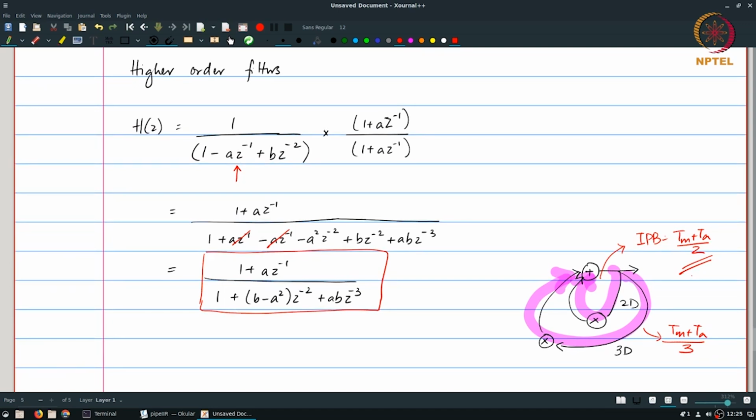So the purpose of this was to show that there are certain kinds of situations in which we can make fundamental changes to the structure of the architecture that we get for a signal processing algorithm. The property of iteration period bound that was derived is something quite fundamental and is not to be taken lightly. It sets fundamental limits on the best sample period or sample interval that can be used for the system. Changing that is not possible through the regular manipulations or transformations. Pipelining, parallelism, all of those always respect the iteration period bound and do not try to change it.